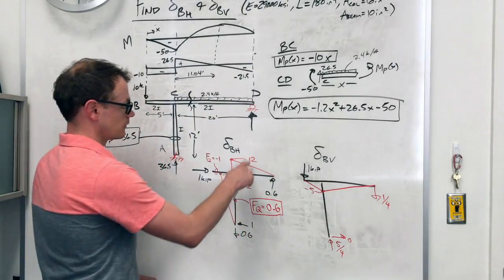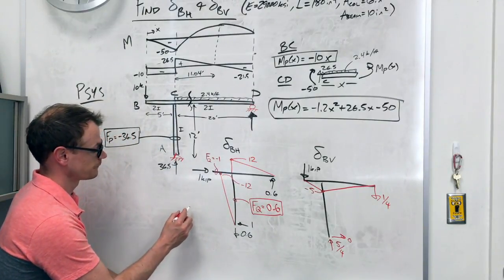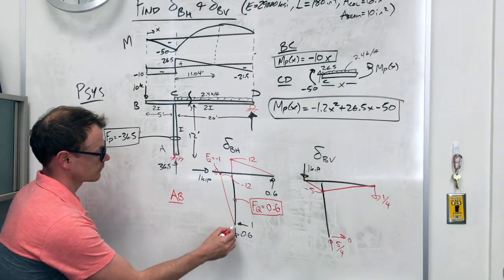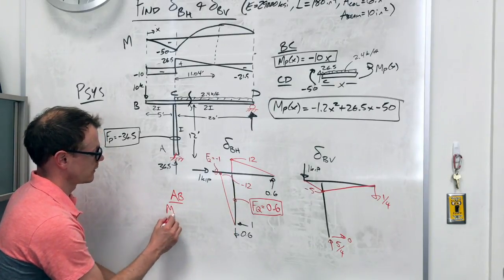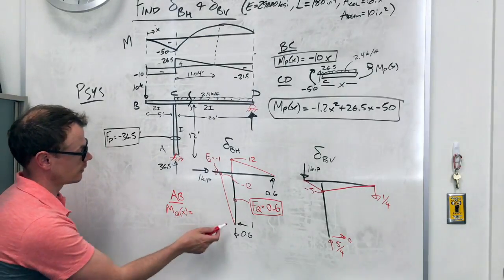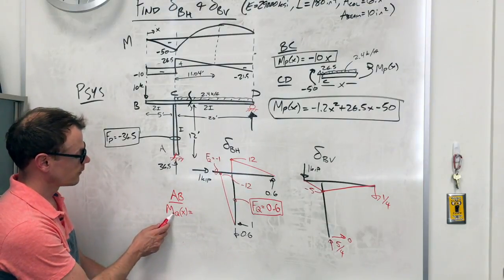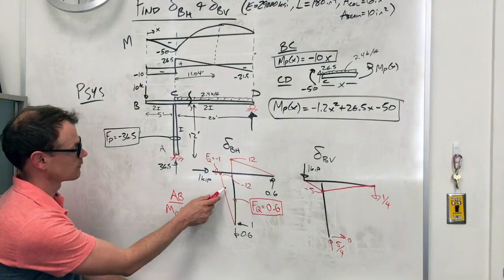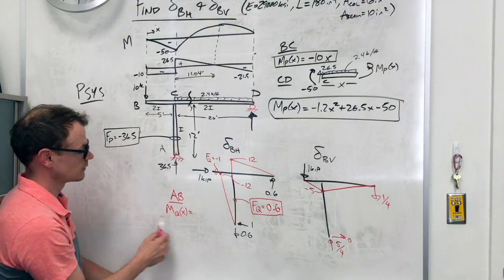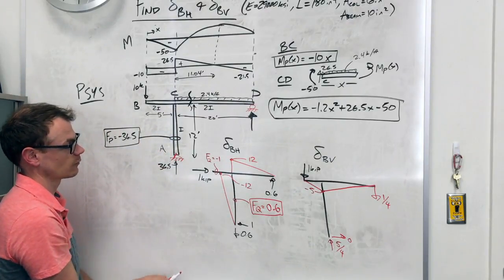Good. These moment equations are pretty easy to write. So let's say for AB, that's this one, we have MQ, x going from, actually, do I care? Do I care if there's any moment right here? No, because it's going to be MQ times MP, and there's no MP, so let's not bother doing that one. Save ourselves some work.